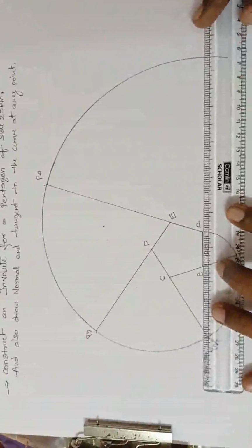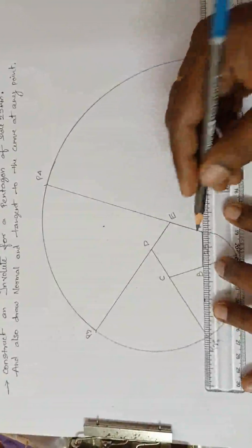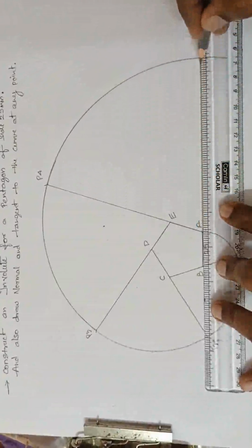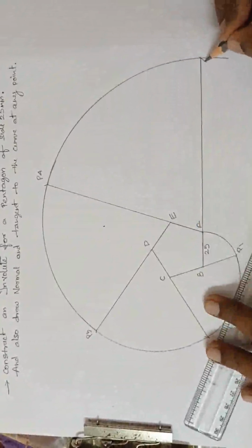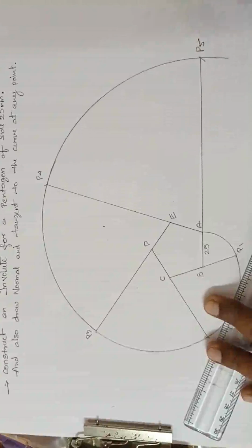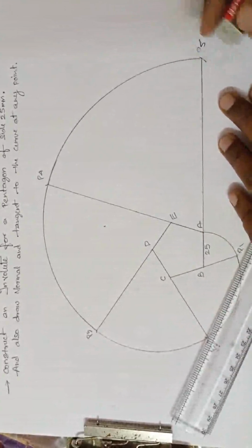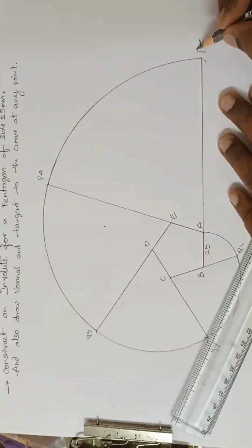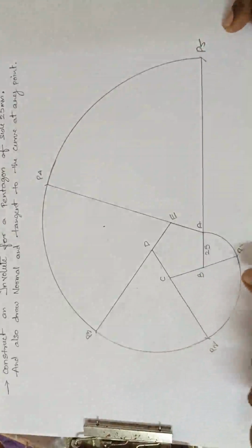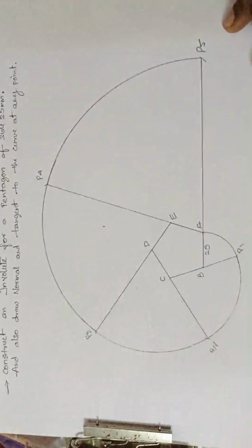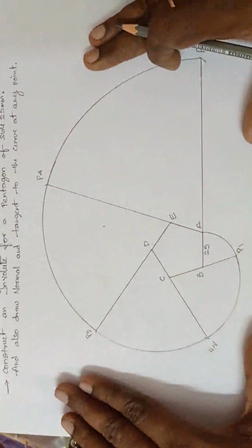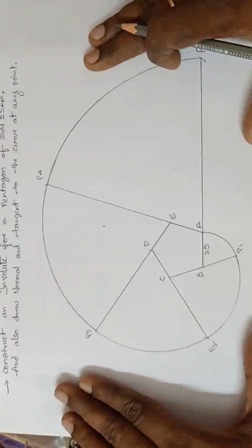You have got something like this. Now up to where we have to draw this edge AB. Now I am drawing like this. What is this point? This is P5, and erase this extra curve. This curve should be up to P5 and write it properly. This is P5. Whatever you are writing, the points P1, P2, P3, P4, it should be dark. It should appear very, very clearly.